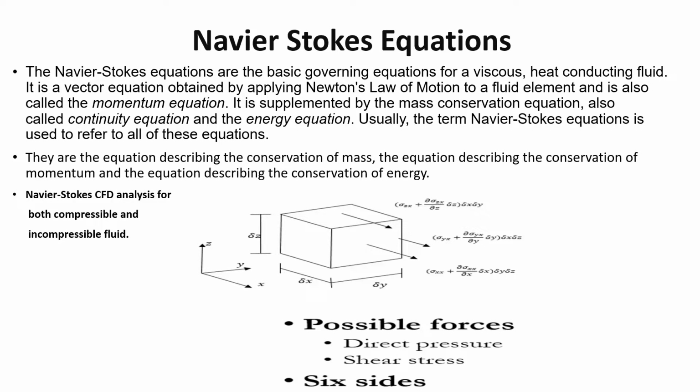The simplification of these factors is the clue to understanding the physics of flow in different fluid systems. One way to easily do this is with the help of the Navier-Stokes equations. These are also governing equations in CFD. Navier-Stokes CFD analysis applies to both compressible and incompressible fluids. Navier-Stokes equations describe all of the forces and motion that can act on a fluid.